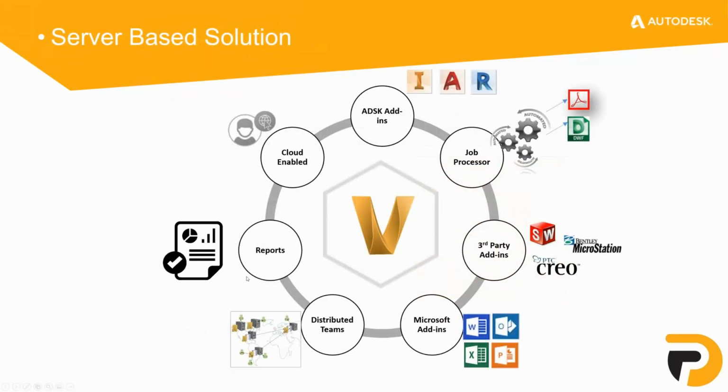So, next page, just some of the features of Vault. Vault can be enabled in the cloud. You could install a Vault on a cloud server if needs be. You have Vault Autodesk add-ins for Inventor, AutoCAD, Revit, etc. You have the job processor for creating custom jobs, like automatically publishing PDFs and DWFs. There's some third-party add-ins like SolidWorks, PTC Creo, which used to be Pro Engineer Wildfire, and Bentley MicroStation. Some of Autodesk's competitors there, but you can still implement those CAD applications with Autodesk's Vault. The add-ins for Microsoft Office,